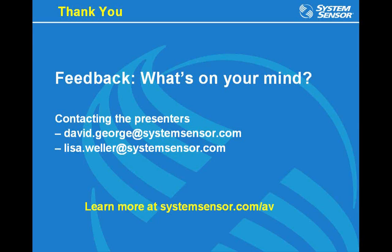This attendee is following up on your comment about speakers in tall ceiling environments. Specifically, for ceilings greater than 20 feet, where should the speakers be placed? For ceilings 20 feet or greater, for intelligibility, it is recommended that those speakers be located on the wall. And the height is determined by the code or by the AHJ, right? Well, the height on the wall is determined by NFPA. It says that the speakers need to be at a minimum of 90 inches above the ground and at least 6 inches below the ceiling.